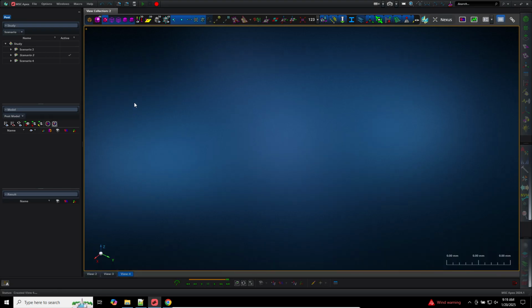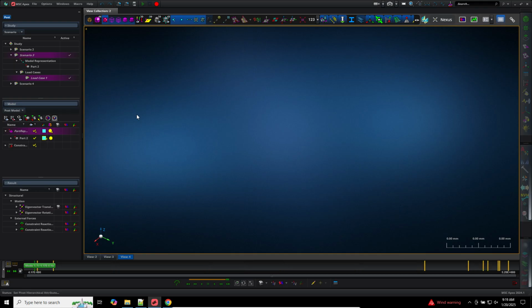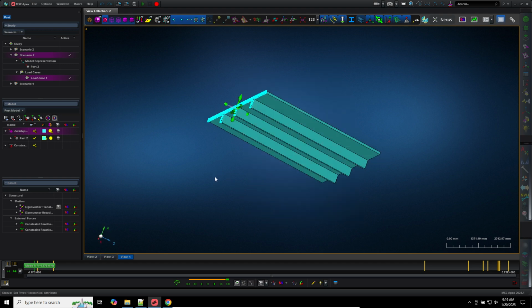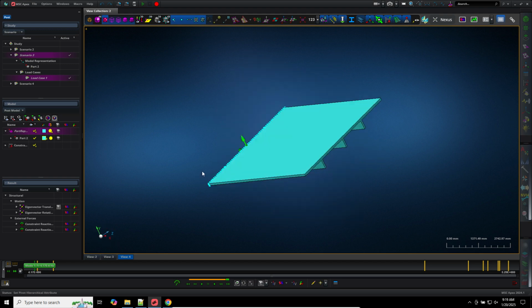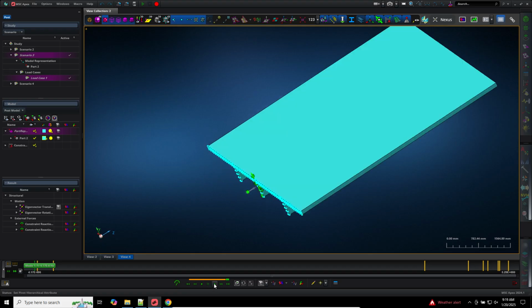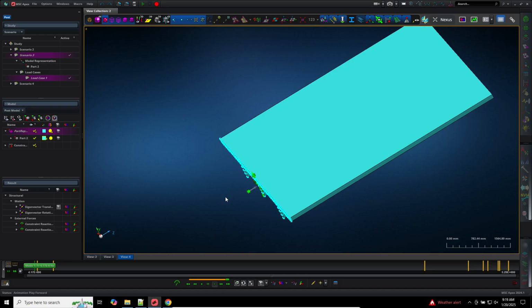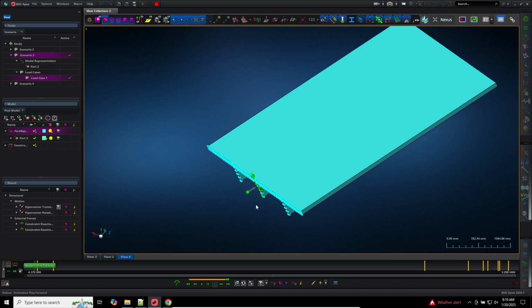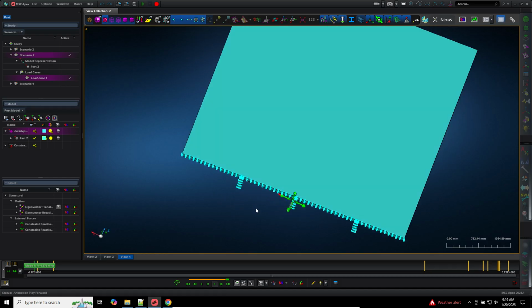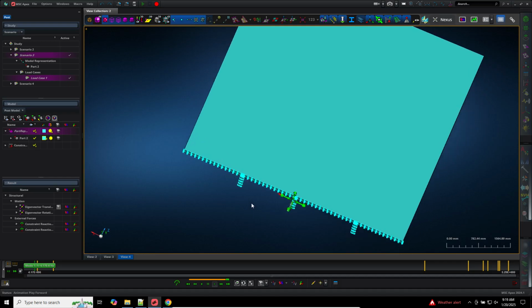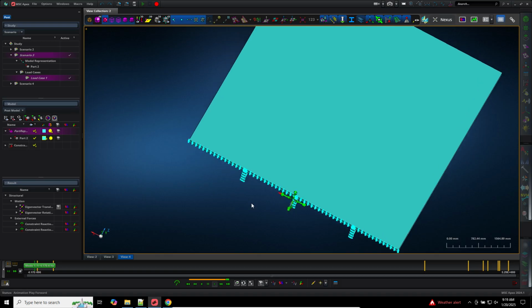I'm not a big fan of this side by side, just because you can see how confusing it is to operate it. Okay, now this is the problematic configuration. Let's look at what the modes look like here. So we're going to animate this. And remember, the third degree of freedom is not properly constrained. So you can see that we either have translation along the Z or we have rotation about the Y-axis. And here this mode is telling us, hey, you have rotation about the Y-axis.